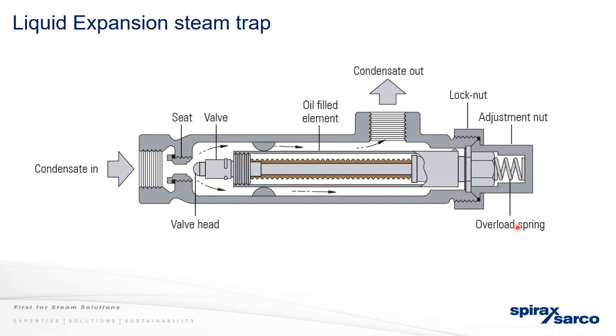They dump quite a lot. It's an oil-filled element, so it's quite robust. But yeah, it can remove quite large quantities of air as well as cold condensate. So perfect for startup, as we said.